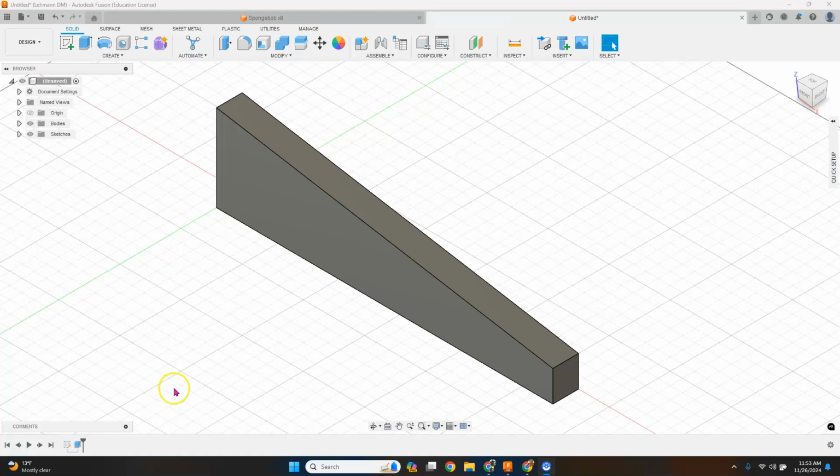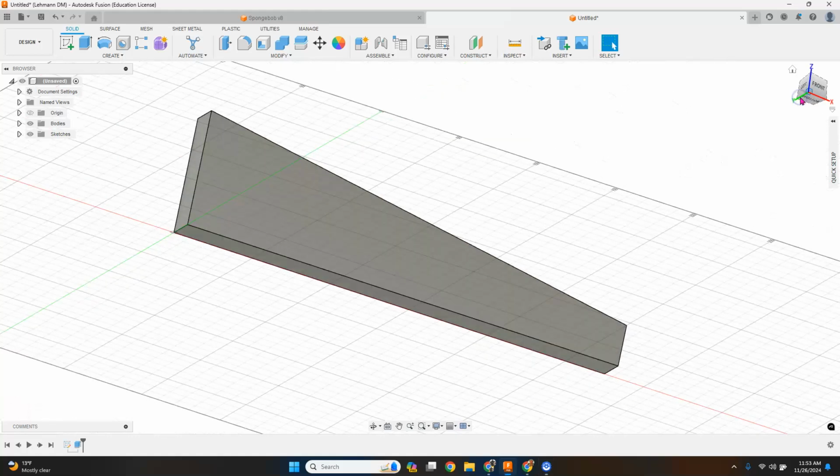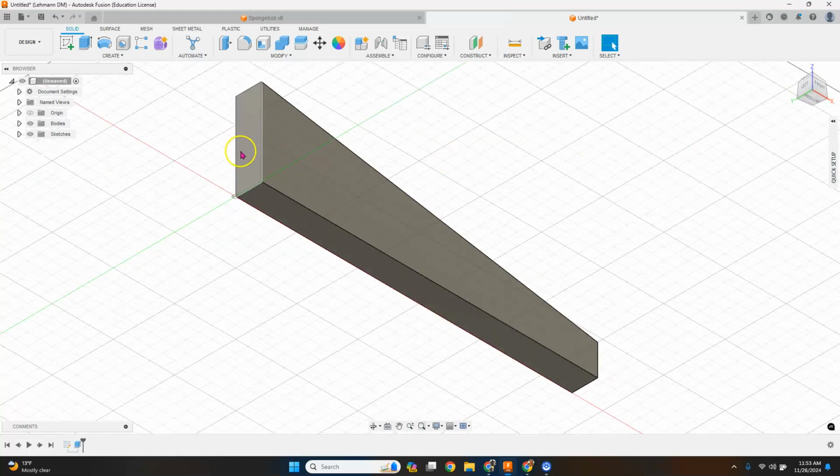Hey everyone, in this video we're going to continue on our CO2 car block. The thing we're trying to get done right away here today is put a guideline or a construction line going across here at 7 millimeters where we can put axle holes later. And then we also want to go to our back side, which I think is down here in this opposite corner, and draw an arc on the inside, which we'll pull out or extrude out for the CO2 car cylinder hole.